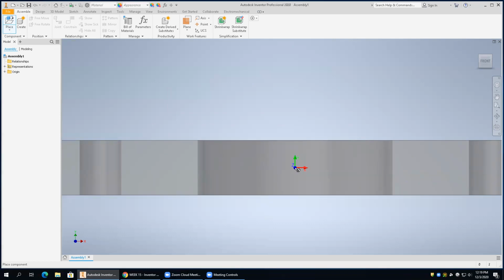The only difference is when you bring a block in AutoCAD, it now becomes part of that drawing file. And so you're actually inside that drawing file. So if I manipulate the other drawing outside, it doesn't manipulate the model inside. In this case, they're linked. So if we open up the base plate file, it'll update the one that's in the assembly file. So there's a big difference, but they're similar. You get the idea?